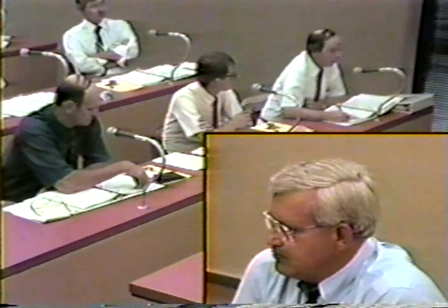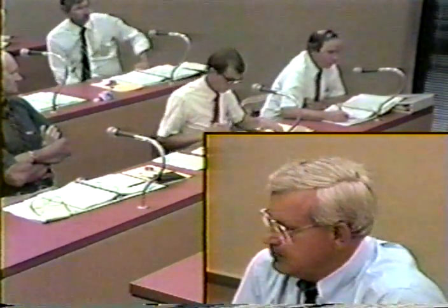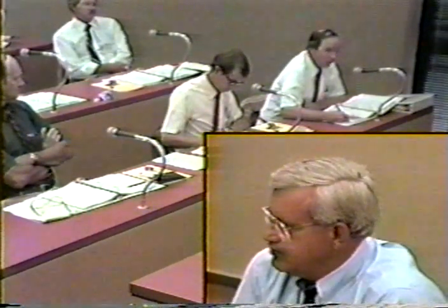When you can't use rock, I think it's important that the maintenance people understand that they must grade the surface of the berm to drain water away. Excellent point. So that water does not pond. Too often there's a tendency to put a reverse grade and think that they're going to channel the water away on the interface between the embankment and the berm. That's wrong. Also, I think you have to consider whether or not you're going to compact the berm. I think that has to be clearly understood before people go out and start putting berm material in, because that, again, influences the weight.